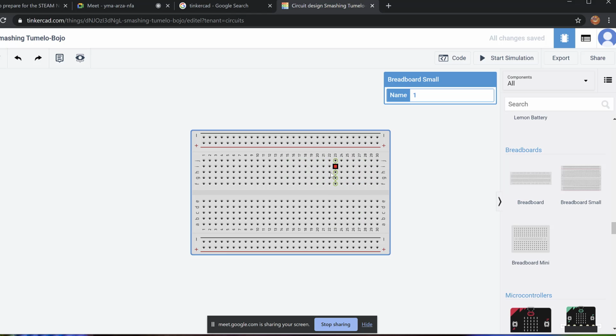The same way, I'm gonna go over how this breadboard is used. It's a plastic board made of a bunch of holes. Okay, you can see there are some horizontal holes here. Like when I click on the top one, where it says here it's a blue line and it has a minus. Whenever you see green, it means these holes are connected. There is a plate in the bottom. If you plug something here, that point is connected to any point within this row. The same thing for the positive, that blue line here. So when I click on any hole, there is a metallic plate in the bottom that connects each hole.